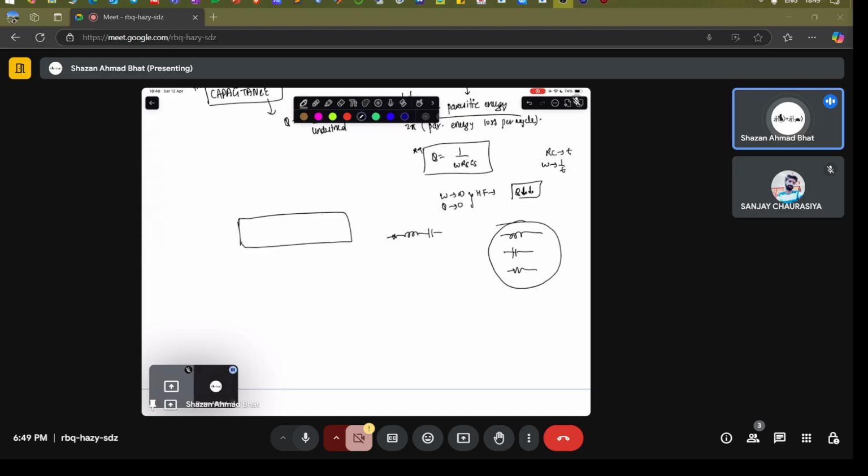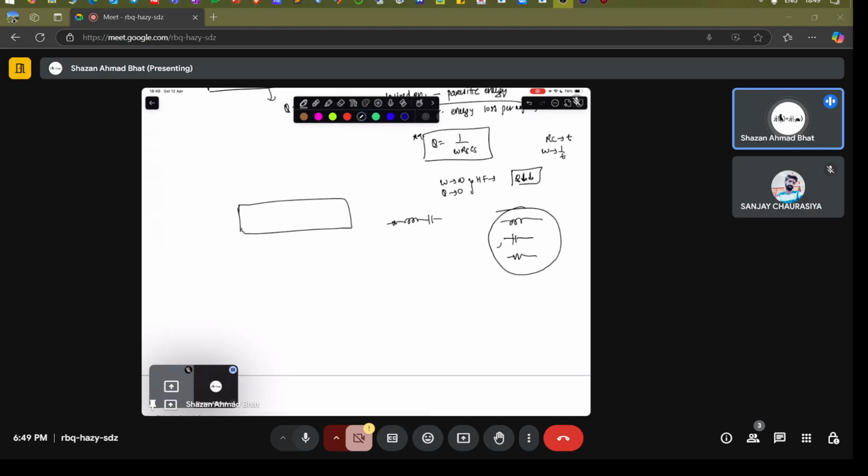The resistor we don't mainly deal with; we're talking about the capacitor and inductor. If the quality factor is high for the capacitor but low for the inductor at a certain frequency, then it's going to be limited by the inductor, because the lowest one always limits this particular ratio.